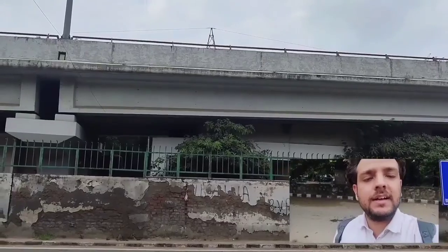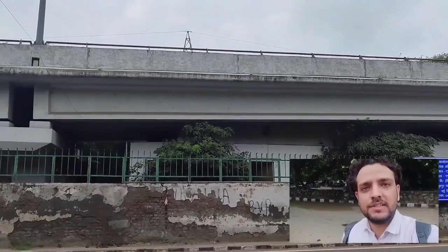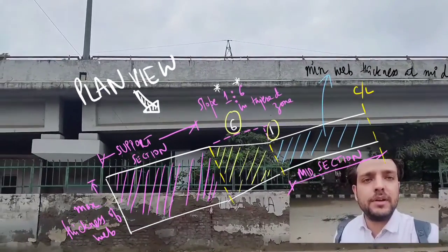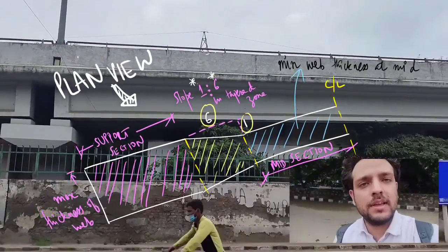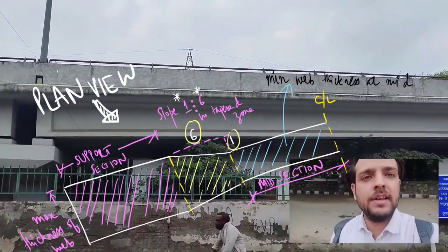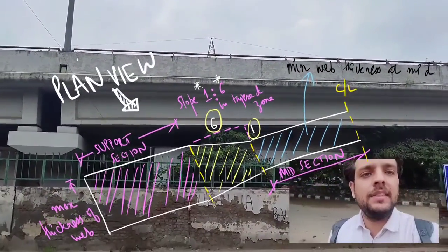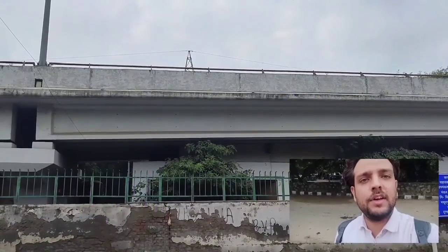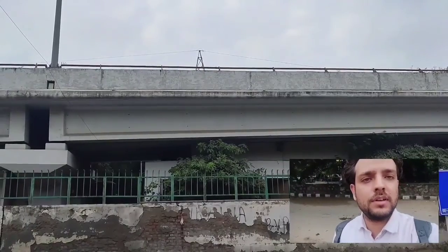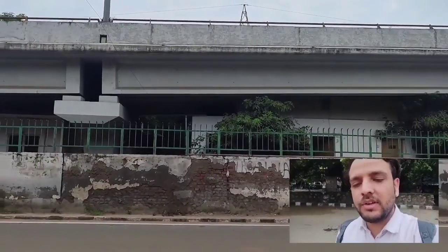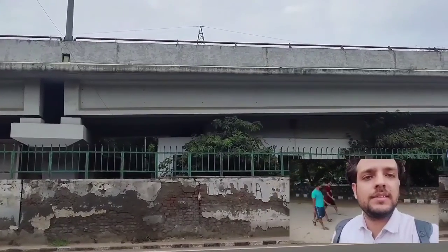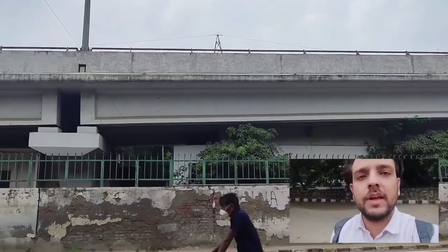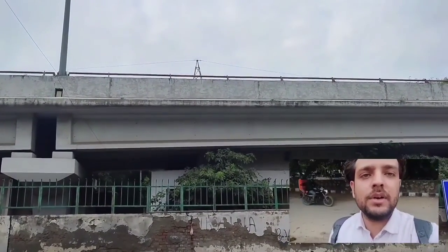And after that, with a uniform slope of 1:6 in plan, as you will see in this sketch, the tapering of the web from a thicker web to a comparatively less thick web is done, and in the midsection your cross-section is something like this, where the web is the thinnest of all the cross-sections. So to ensure gradual tapering, this tapered zone with a minimum slope of 1:6 is recommended. However, the slope can extend gradually but not steeper than 1:6.